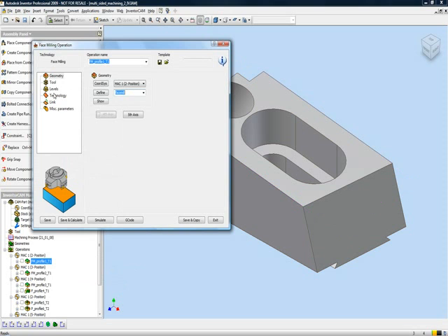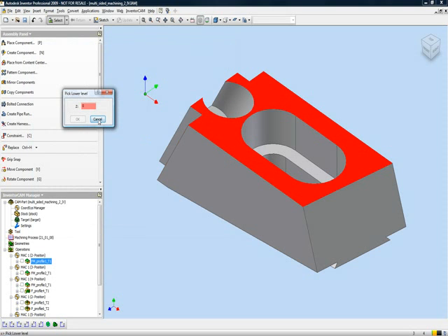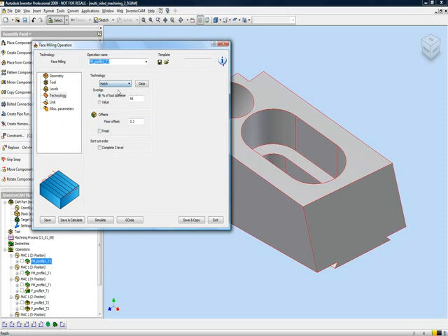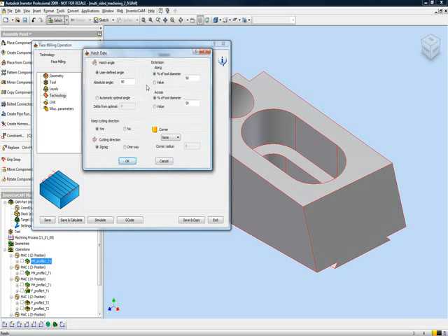The tool that I will be using will be a 16 millimeter end mill. And my levels, we have my upper level of 10 millimeters up until the face depth of this part over here. The 10 millimeters on the upper level is to cover the excess material that I have on top. Now in my technology area, I'll be working in a hatch fashion. And if I go into my data, I've chosen to work at an angle of 90 degrees, in other words, going back and forth this way on the part because I'm using zigzag.